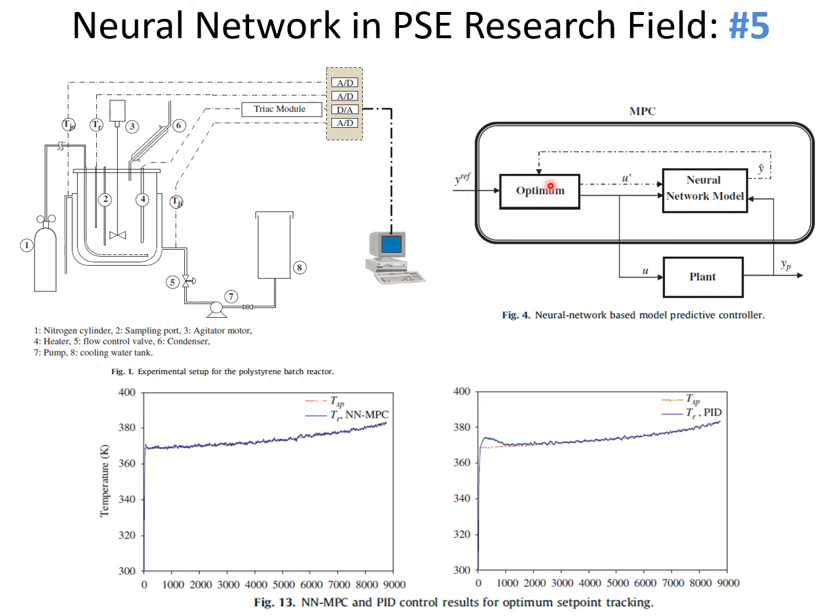The optimizer uses the model to come up with the control inputs to be used to control the system, with many values for the future, but normally we implement the first one, then we go again to get the next one and implement the first one. Normally we give a profile called a horizon of values, but the implementation is normally one.